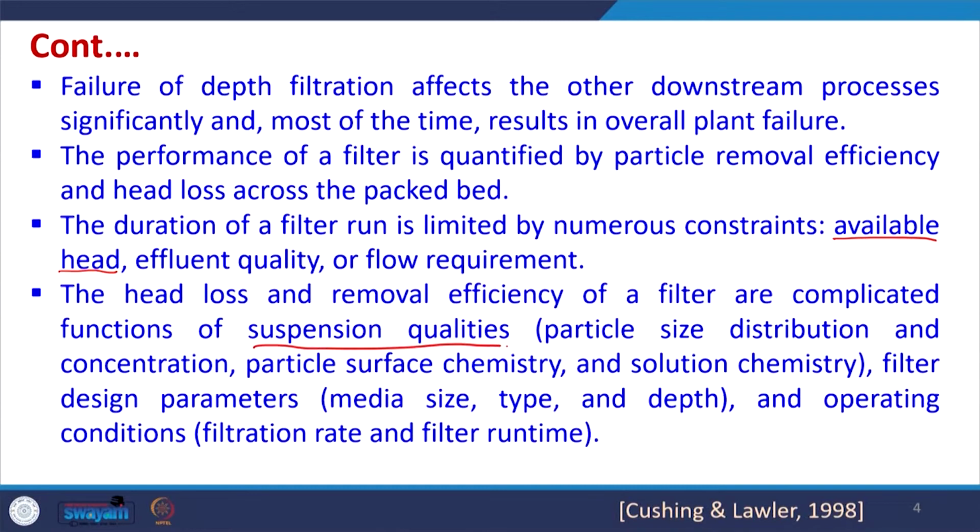This will also be dependent upon how much volume of water has to be filtered out in the filtration unit. So, this is an important consideration, and all these have to be taken care of. The head loss and removal efficiency of a filter are complicated functions of various parameters, including the suspension qualities, okay, and the filter design parameters. So, all these are important.